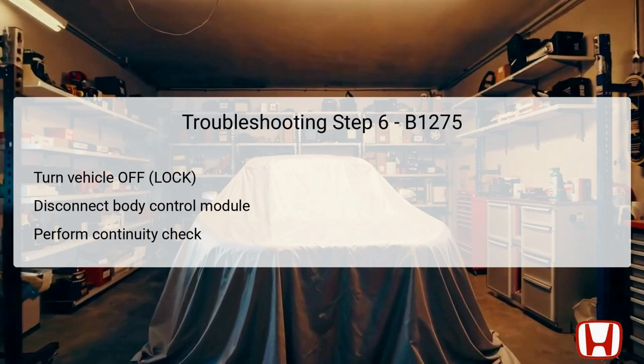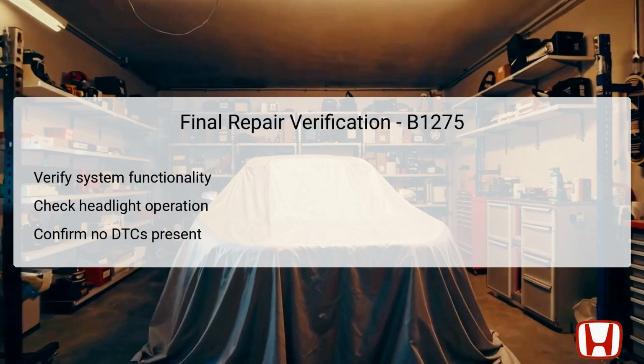If you find continuity, it confirms that the wires are functioning correctly, indicating a possible malfunction within the body control module. Conversely, if continuity is absent, it means there is an open wire or high resistance problem within the circuits, necessitating appropriate repairs.